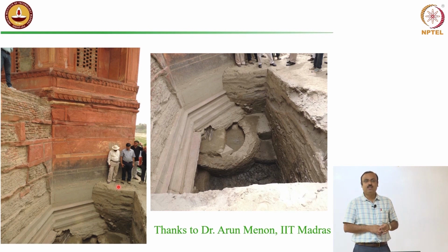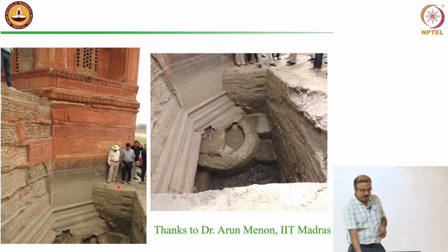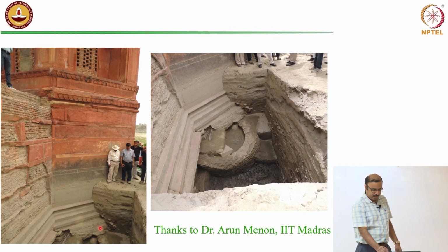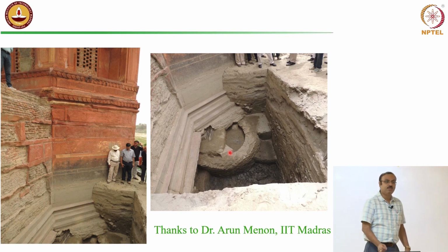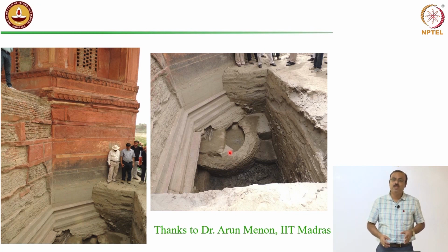The Archaeological Survey of India excavated a part of the side of the Taj Mahal, and what we saw here is very interesting. So this is the excavation we did, and this is the base of the structure, and this is what the foundation is. Is this kind of well type of shape? Have you seen this? This is a well. So this is a special type of foundation element. It's called well foundation. It's just like your regular wells.